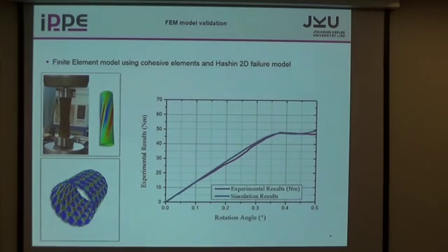When we talk about the numericals of the finite element model, it's a step forward in understanding the failure of the braided composites, especially the thin wall tubes. We had a lot of discussion whether or not they could actually warp like this. We first developed the model and then we performed the tests. We got this warping in the finite element simulation, and my colleague said it's not possible. It's not warping, it has to crack. And I told him, yes, if it's thicker, it will crack, but if it's very thin, high chances that it warps. In the end, in the test, it turned out that indeed the thin wall tubes failed by warping and yarn failure, so the interface between yarns fails and they lose structural integrity.